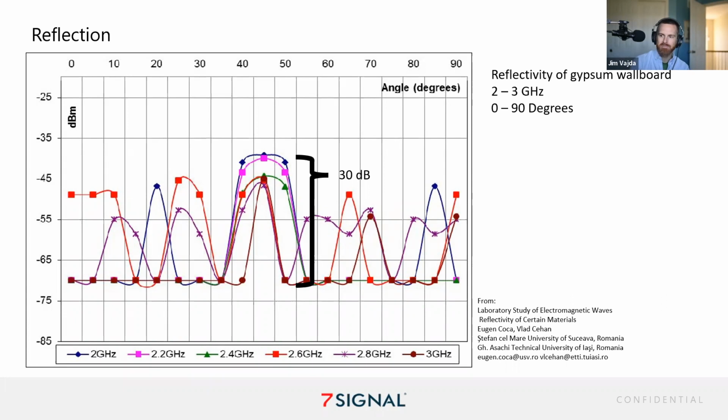Particularly with drywall, I just thought, well, it's 2 or 3 dB of absorption, and that's all you have to think about. Plus, if it's indoor, there's multipath. Well, if this is the most common building material we're encountering, it's got to be the source of some of that reflection, right? It is a surprising amount, though, for sure.